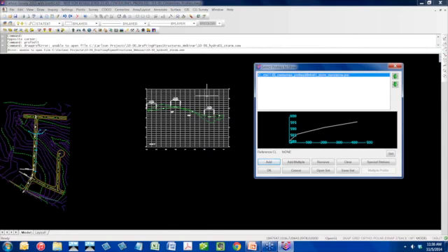Manholes 1, 2, and 3 go parallel to this center line, so you could also show these pipes on this profile. What I did, though, is I wanted to see one standalone pipe profile run that went from 1 to 2 to 3 out to here, so it actually went perpendicular to the center line. So I'm going to draw this on a whole new profile grid.